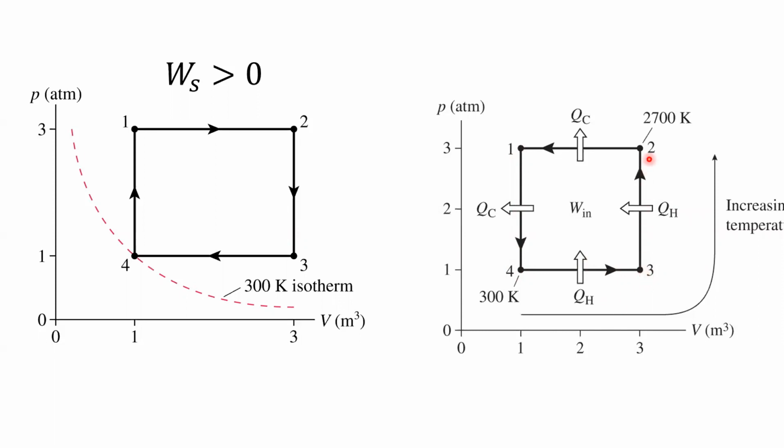See how it's an isochoric process? So that means no work is being done on the gas. We're not squeezing the gas and doing work on it, and yet its temperature has clearly shot up. We're going from one isotherm to another. How can you raise the energy of a gas without squeezing it and doing work on it? You would have to transfer heat into it. So the arrows make sense.